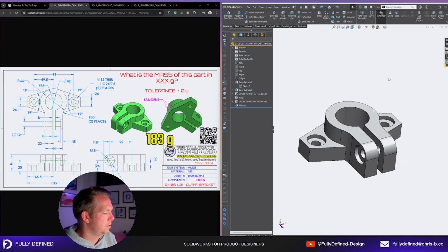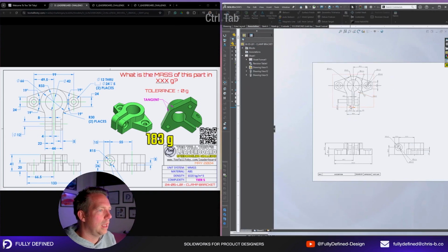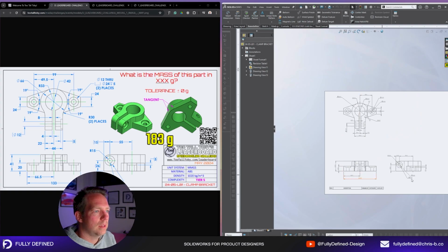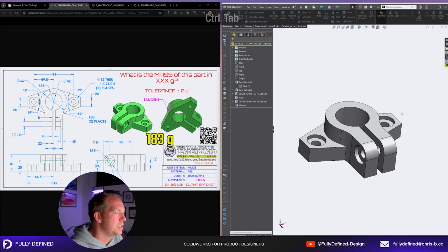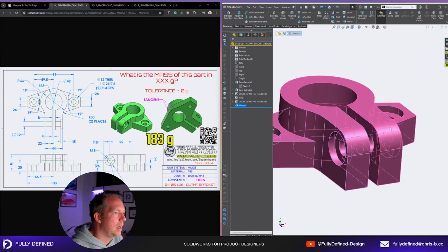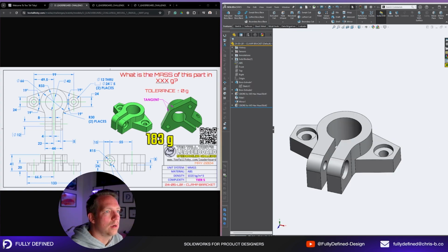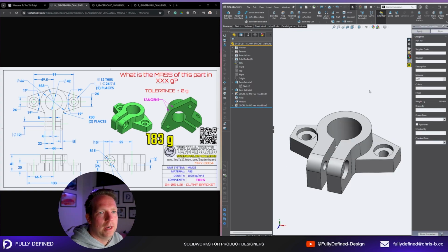Found my issue. So that counter bore there, that's not a match. It's only one side. So that's why I was missing that, which means where that mirror happens, I need to do that fillet beforehand, before the mirror, but that counter bore needs to be afterwards. There we go. So easy solution, and then we've got 183.